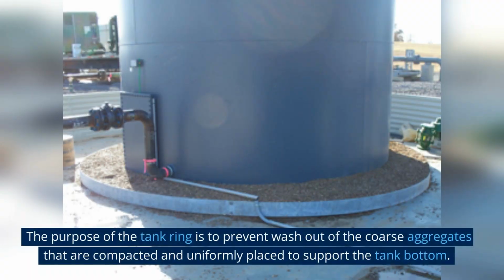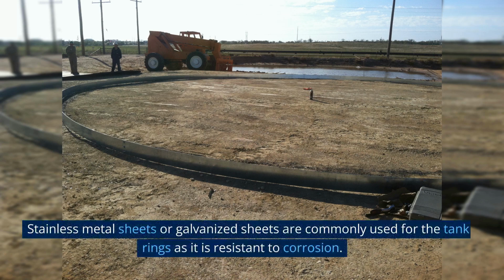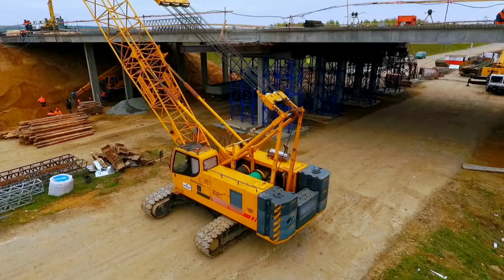The purpose of the tank ring is to prevent wash out of the coarse aggregates that are compacted and uniformly placed to support the tank bottom. Stainless metal sheets or galvanized sheets are commonly used for the tank rings as they are resistant to corrosion.